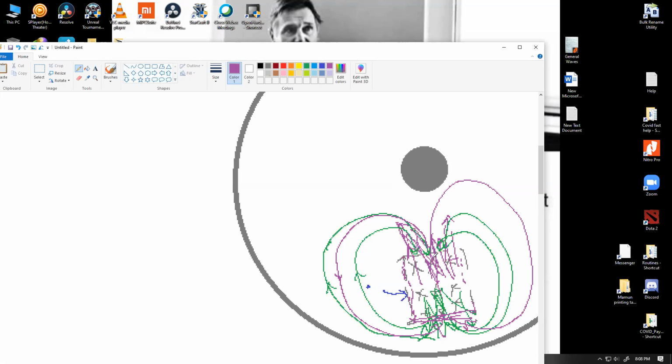Now, if you wonder where this heat energy is coming from: energy is indestructible, it cannot be created, it can only be converted from another form. So this heat energy will be coming from the kinetic energy of the disk. You have to understand this. The reason the electrons are moving like this is because the disk was rotating in the first place. If the disk did not rotate, these electrons would not have any reason to move. They could pretty much be stationary within a stationary magnetic field. The only reason the electrons are made to move is the rotation of the disk and the simultaneous presence of the magnetic field. So the disk had some kinetic energy to begin with.